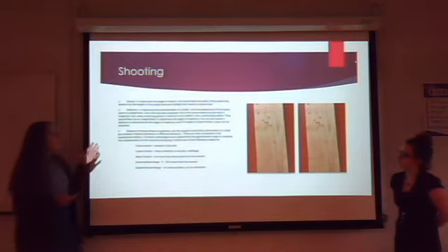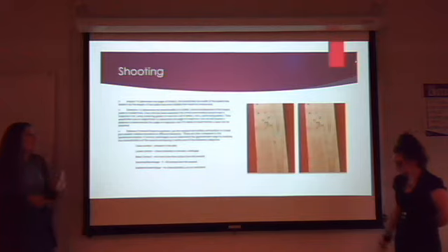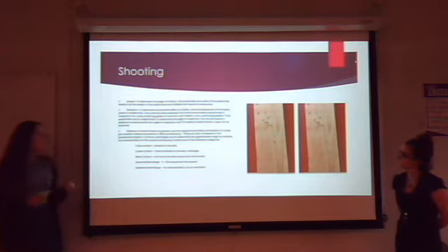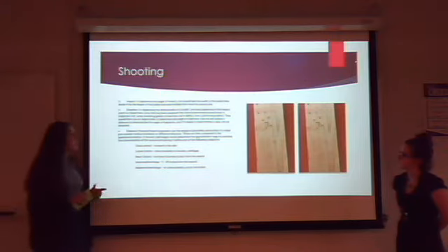So on this slide, you can see the impact. You would determine the impact angle. One would take the width of the defect itself, divide it by the length, and then take the inverse sine of the result, which would give you the angle of impact.